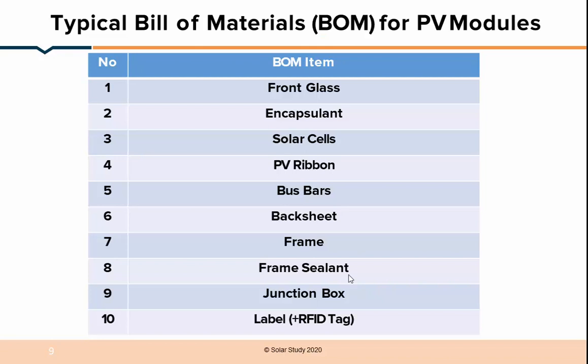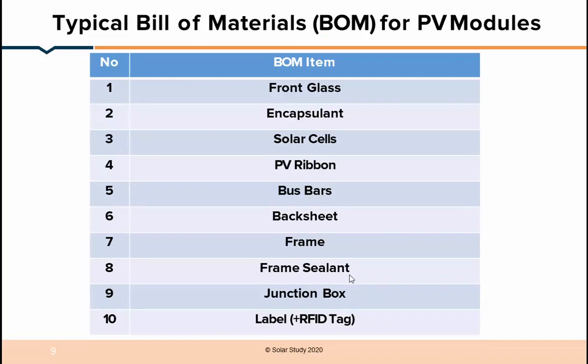While manufacturing in a plant, we are manufacturing so many modules per day. So in order to identify which module has been manufactured, we have to do naming. For that naming, an RFID tag is used. It contains the serial number, date of manufacture, everything; you will get all the data. Then sticker. That sticker is like the data sheet, nothing but what is the voltage of that panel, what is the current rating, what is the power rating, all put on the back side. So that is a sticker containing the manufacturer name and all the details.